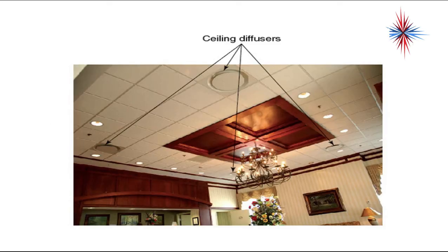Okay, this picture is just an example of ceiling diffusers around a kitchen or living room environment. Keeps it out of the way of the furniture. Where my mouse is, there's a return grill. So we have our outlets, our diffusers, the supply registers. Air is coming into the space around the four corners. It's going to diffuse, cause currents to go on the ground, and then it's going to come back up into the return grill that's sitting right there. Again, this gets rid of stratification because we're moving air in all parts of the room.